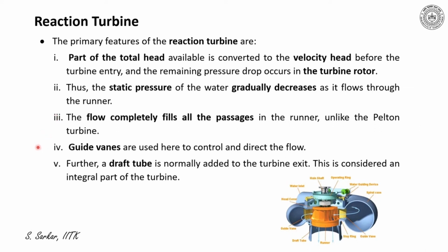Furthermore, the guide vanes are used to control or direct the flow. Further, a draft tube is normally added to the turbine exit. This draft tube is also considered as an integral part of the turbine. So these are the features of a reaction turbine.